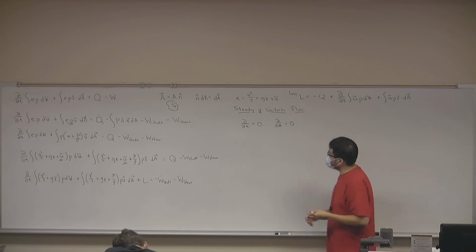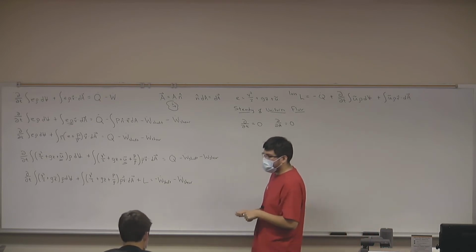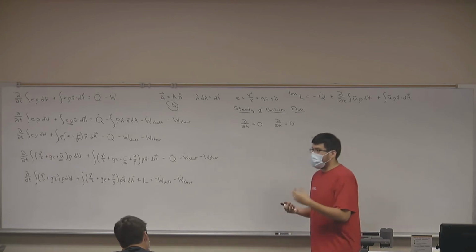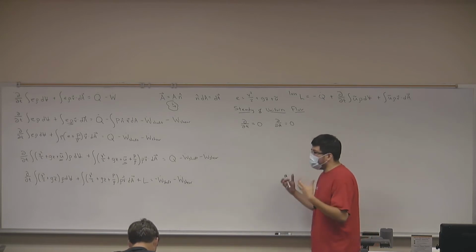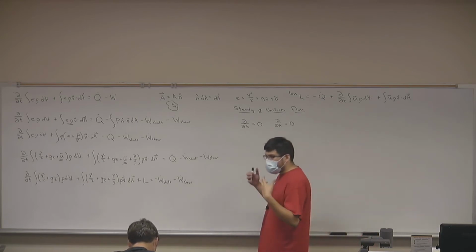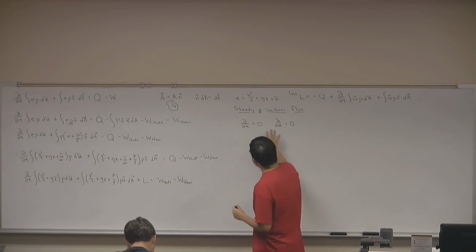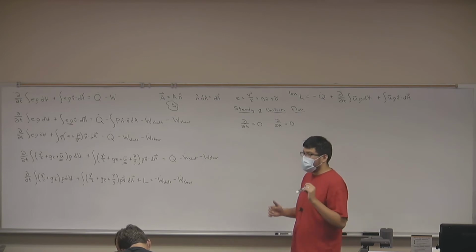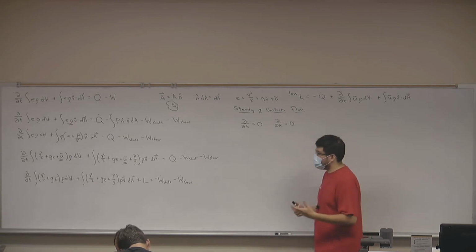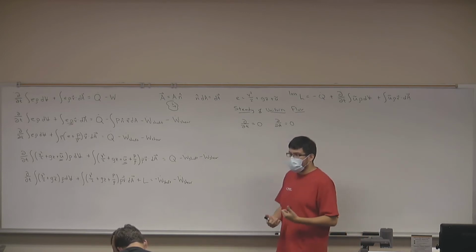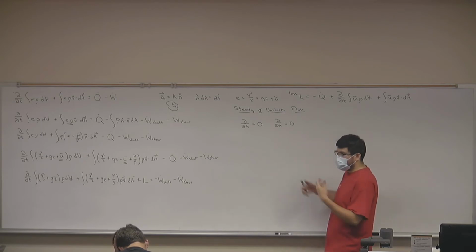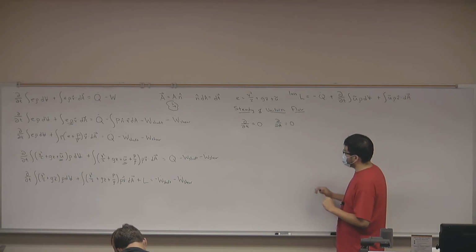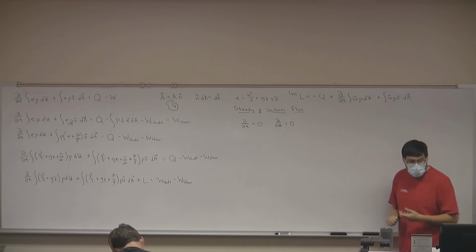And this is actually a very good assumption to make when you're dealing with pipe systems. Of course, we know that the velocity will be greater at the center of the pipe. However, when we're dealing with large systems, where we got thousands and thousands of feet of pipe, it's actually safe to assume that the velocity and other properties are pretty much constant over the cross-section. And here's where I like engineering, right? In engineering, we can make those assumptions. If we were researching, if we were trying to come up with some scientific equation, then we can't. But because we are engineers, we can make those reasonable assumptions.